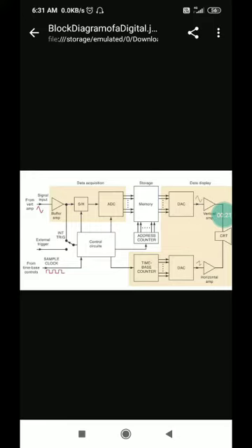You apply the signal that you want to measure, and the CRO will show you the shape of the waveform on the screen. You can set times per division, you can set volts per division on the screen and take measurements. As and when you remove the input signal, the screen will not show you the signal because the signal has been removed. Secondly, the measurements that you are interested in have to be done by an individual. You have to involve yourself in taking measurements.